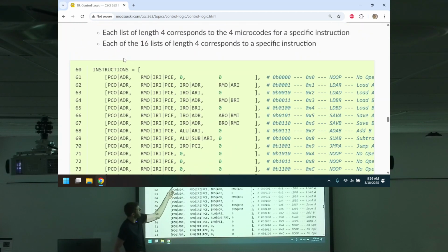I want the bit pattern for program counter out, 0000, 1000, whatever it needs to be. And the address register, whatever bit pattern that is, you OR them together. There will be 17 bits, and only 2 of them will be on. The rest will be zeros.